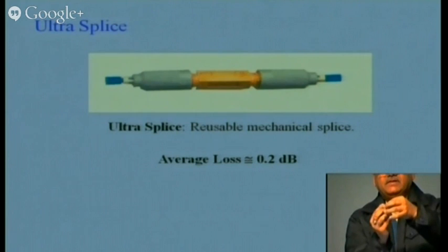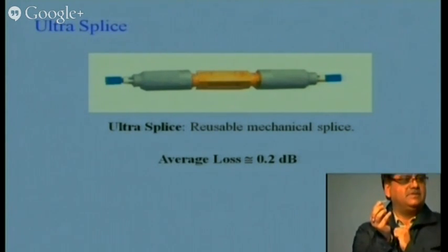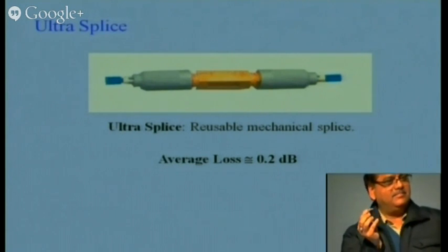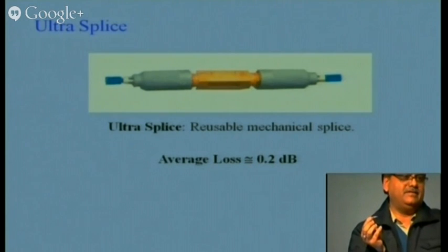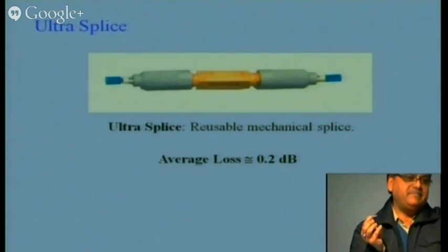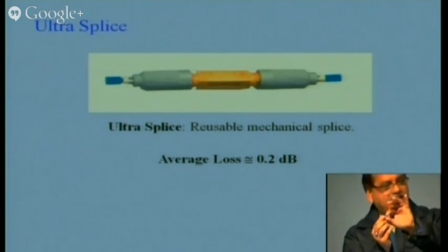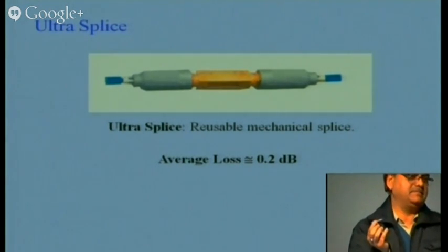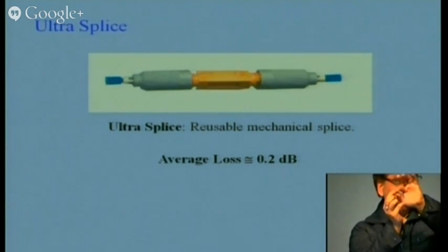So the fiber will be locked at this place. I can leave it there. Whenever my splicing unit is available, I will file a complaint with the splicing unit. They will come to that site and replace it with the permanent splice. So it can be reused because we have used only the screw.